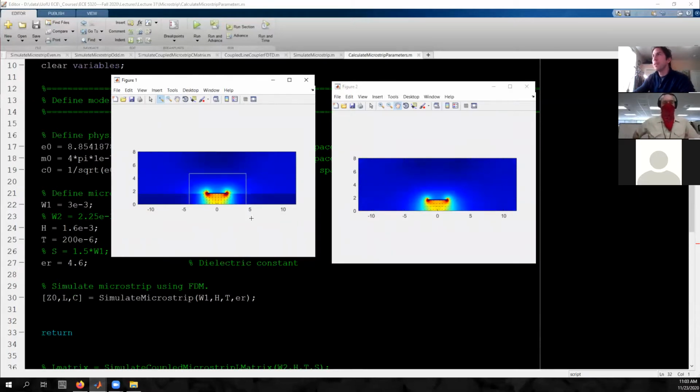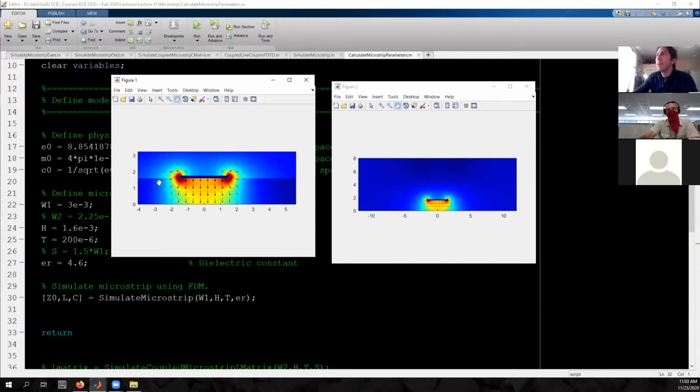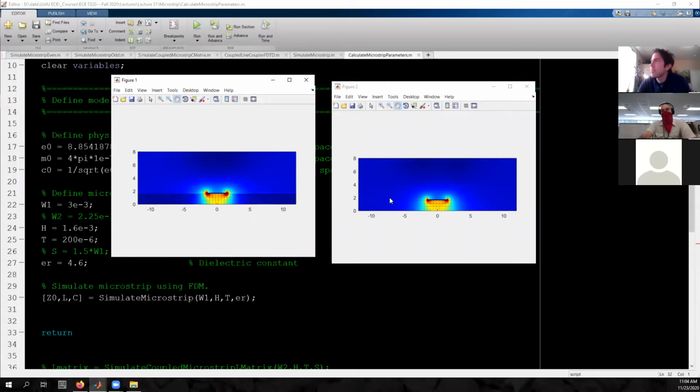So if we zoom in here, you can see that is a little positive strip of copper. It's all at a constant potential, so there's no electric field inside of it. But you can see all the electric field coming out of it. And you can even see the little discontinuity here where there's the dielectric boundary. And you notice I've added all this kind of void space to make sure that there's nothing around it to interfere with the calculation. And so that's the electrostatic simulation.